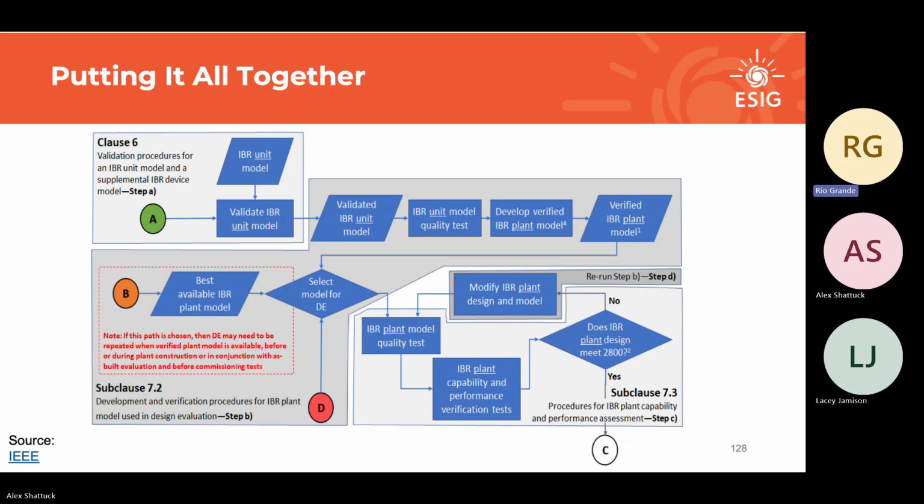So even in the perfect world, you're changing at commissioning, and once COD happens, it's a year until Mod 26, right? So you literally have a year of nothing. Even if Mod 26 fixes stuff, there's a literal year of unknown operation. And then Mod 26 happens, and you're only testing two simple things: a small voltage step and a small frequency disturbance.